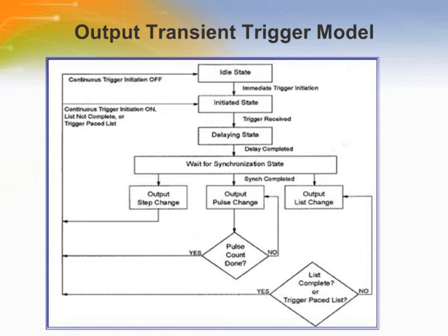Using the 6800 series triggering subsystem, the output can be triggered to turn on at a phase near the peak of the AC cycle for stimulating a worst-case AC-line condition. Simultaneously, the AC source can be triggered to take current measurements to characterize the behavior of the power supply under test. In addition, triggering can be extended to external test equipment via the trigger out connection.